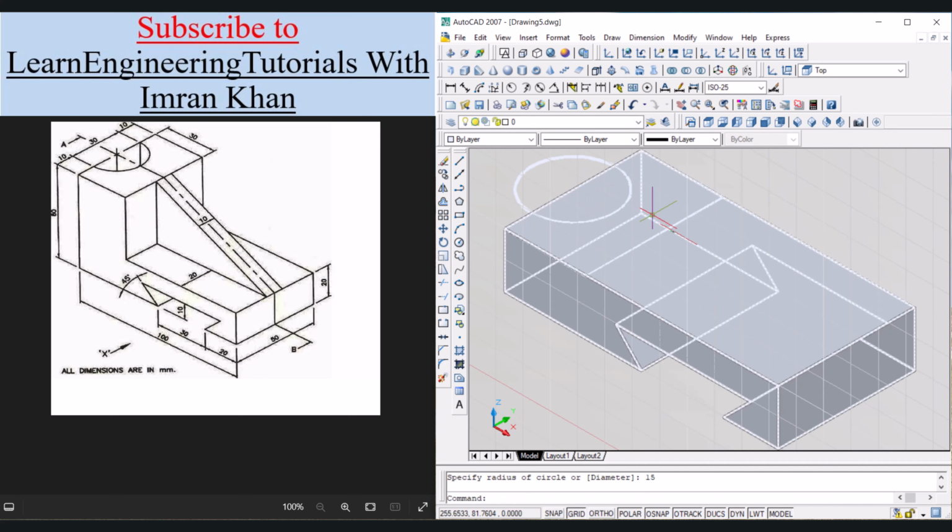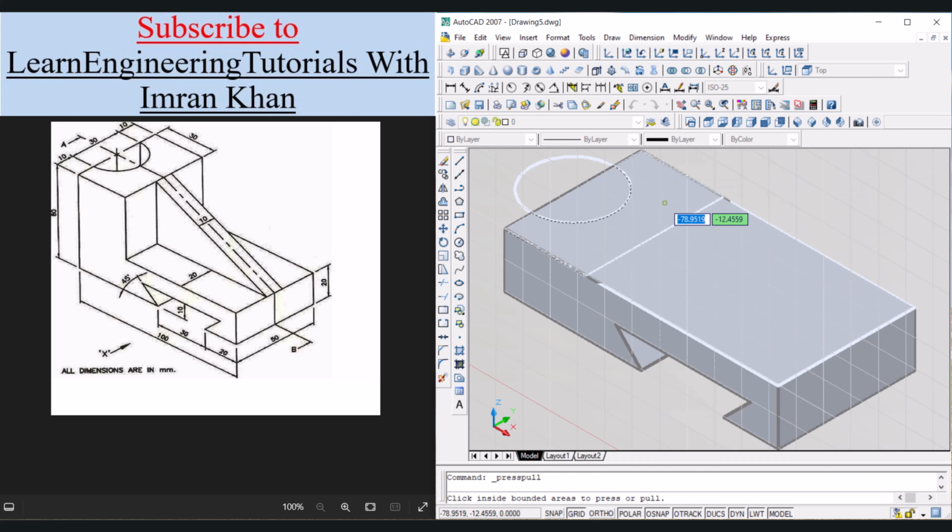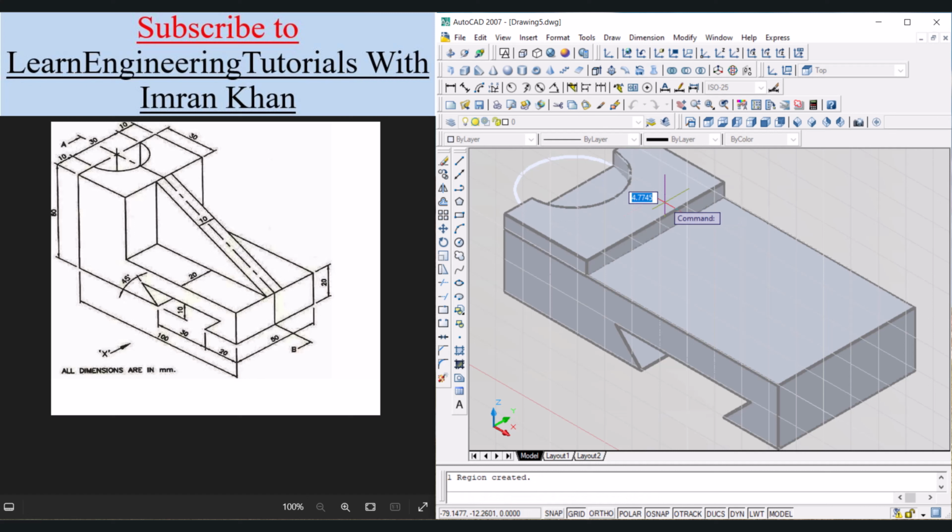Now we have to add this area, so for that we have to add thickness to this area, and we have to remove this area from the below part. So click on press pull, bring the cursor over to this area. We can see this area has been selected. Click, and now in the upward direction we have to write the value of 40, enter.